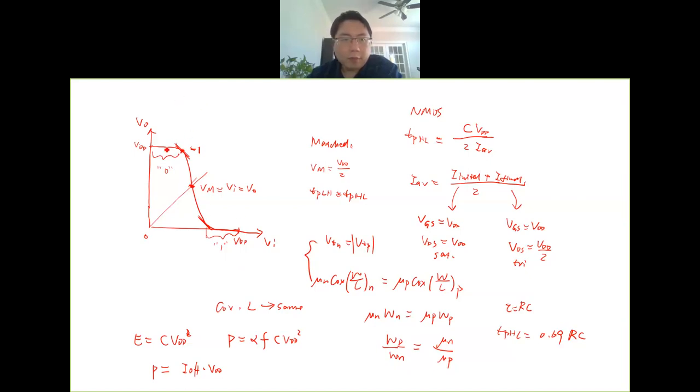So then for the unmatched case, you know this VTC curve will shift to the left or shift to the right, depending on the relative strength of the NMOS and PMOS. So if NMOS is stronger, then the VTC curve will shift to the left. Why is that? Because NMOS is for pull down. So if NMOS is stronger, for example, this part is larger than this part, then the NMOS will pull down the output earlier. So then this VTC curve will shift to the left.